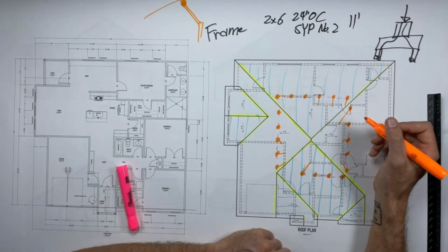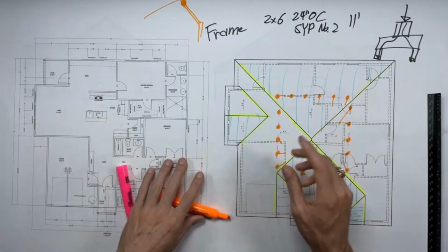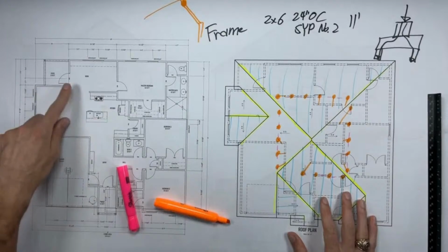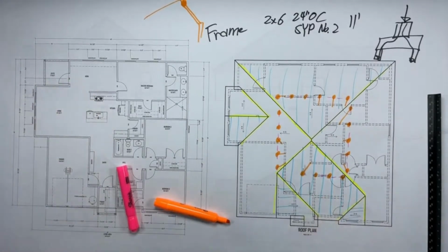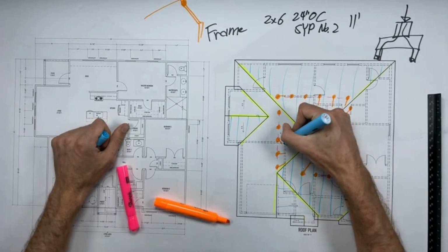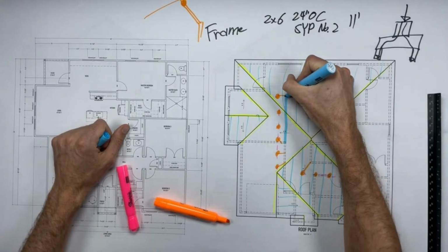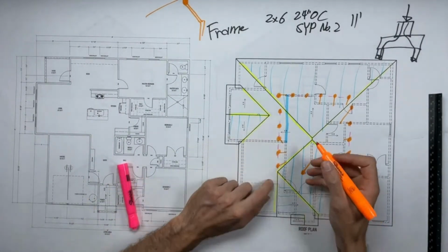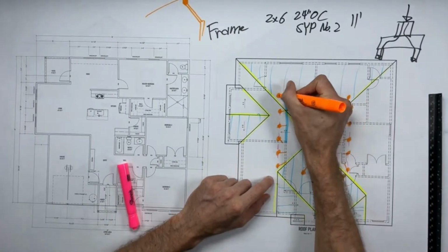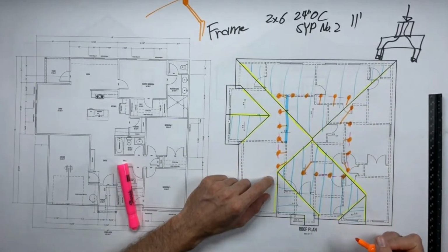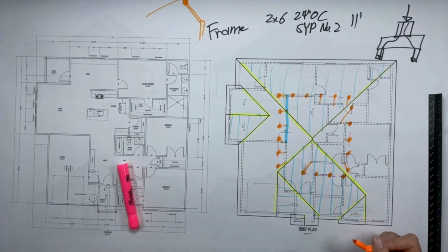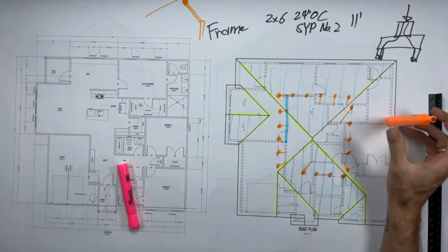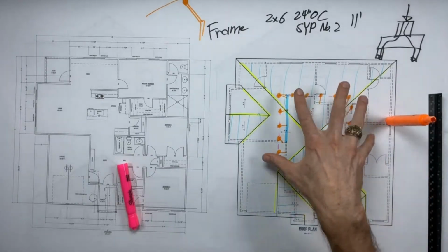And even if it couldn't, I'm going to need something for the ceiling over here. So I happen to know I'm going to need a beam somewhere in here because I've just got a big open space. I need something. So we're going to put a beam in right here. That's our beam. That beam is going to be at the ceiling height, flush with the ceiling, so you don't see it when you're in the house. But now we have a load-bearing member to put all this weight on. So we can put our purlins on that if we needed to. Purlin braces can go straight down onto that. Okay, so that's good. Our rafters are now good.